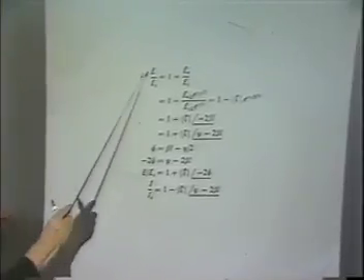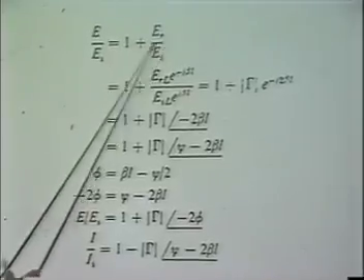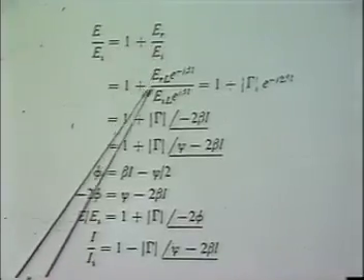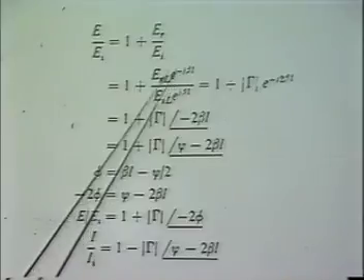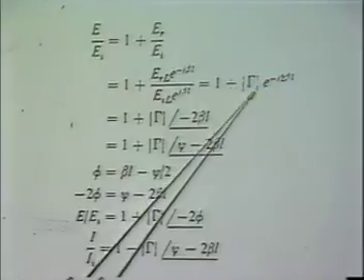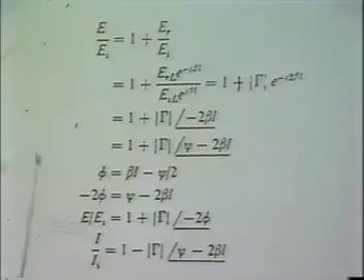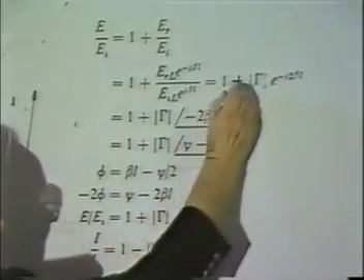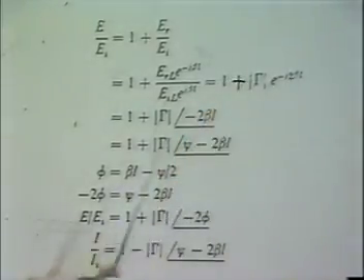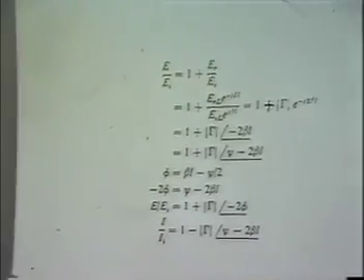See, now notice, the total voltage, if you normalize this, this was E sub I, you have 1 plus E sub R over E sub I, which is gamma. Now, gamma from the load, this is the minus, this is the plus. When you add it up, you get what I showed you before. Gamma, that's a plus incidentally. 1 plus gamma at this angle. Now all that tells you is you look at this as a constant 1, the incident voltage. Gamma is on top of that rotating at 2 beta L. That's going to be the chart.